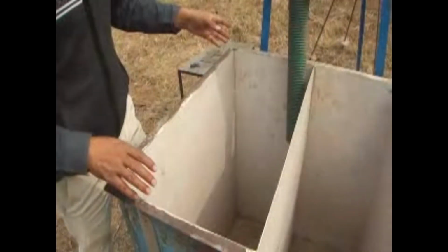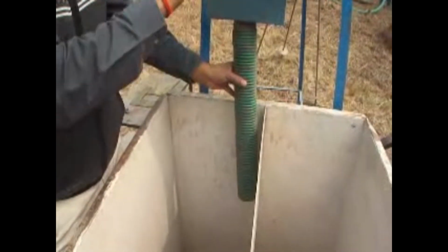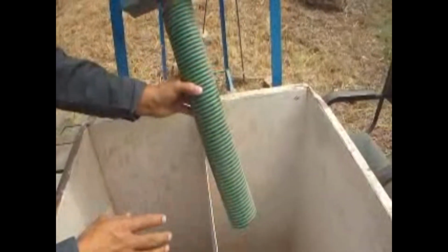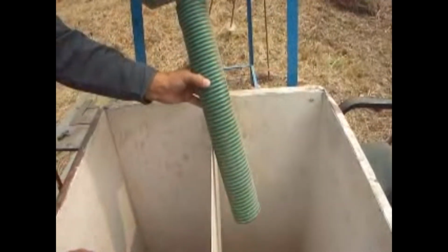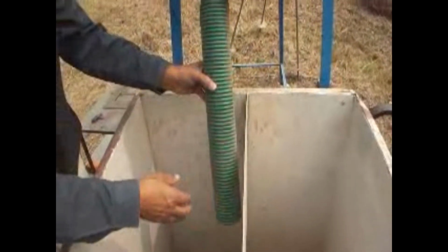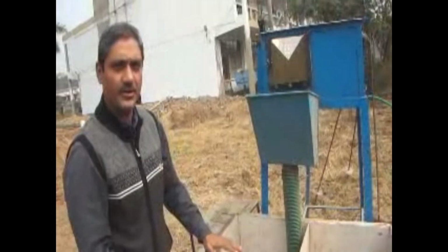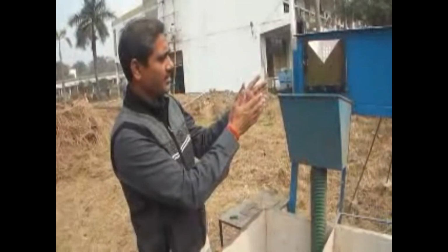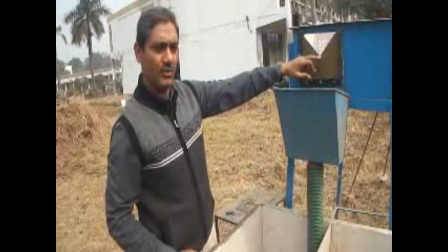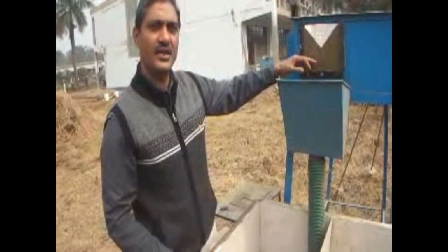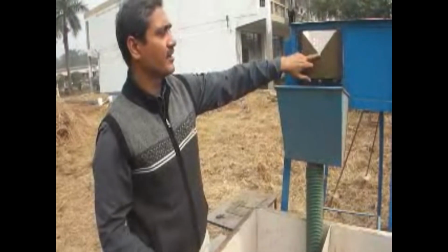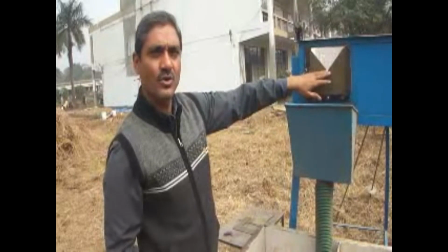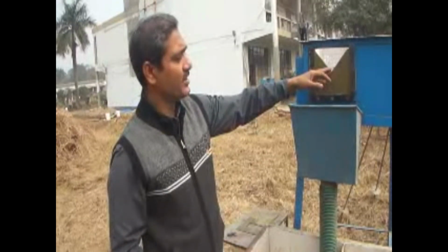We have this arrangement, and to measure precisely for 30 seconds, 1 minute or 2 minutes, we will remove this and another. In this manner we are simply collecting the discharge over the crest into this tank. Now let me show you how the head is measured over this crest and where it is measured. As I told in the class, at least 4H behind the crest we need to measure the head, and how the water is supplied so that it is passing over this crest.